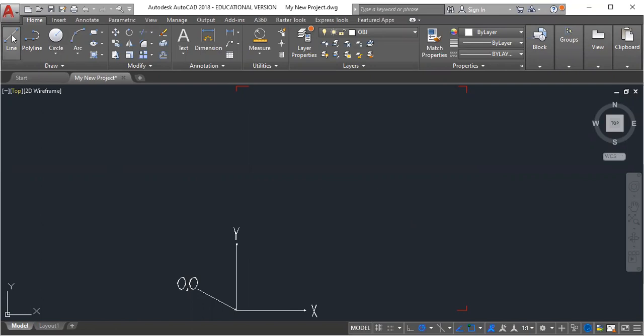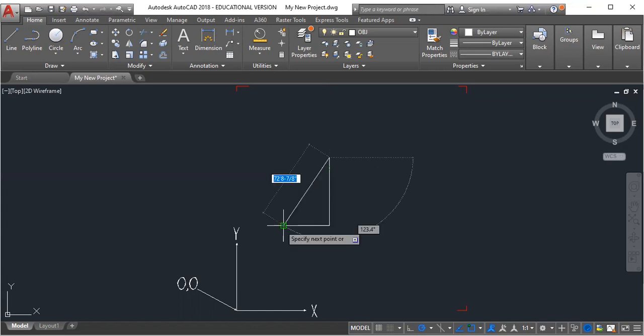In our previous lines video, we did a rectangle production that we call around the block, which is starting at a base point drawing lines. I drew a line, if I recall, 40 feet across, and then it was 60 feet 9 inches up. And then we used the inference tool to use an object snap on that inference. And then because we're in polar coordinates, use that there and snap down to close that rectangle.